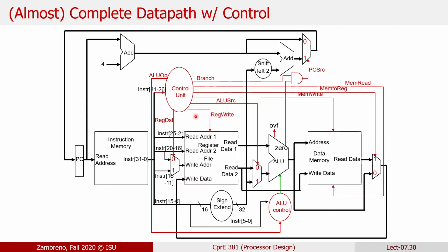We don't always show this in our design because it makes the diagram look pretty messy, right? There's just a lot of wires going on, and you're just connecting those all. In your own diagram, I would just recommend labeling, as it was previously, the control signals next to the muxes in which they're being connected, and just be very clear with what your actual naming convention is going to be.